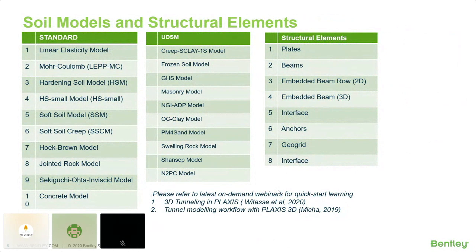Apart from soil, which is a continuum element, we also need structural elements. So we also have different types of structural elements, such as beam elements or plate elements. Plate elements will be very useful in modeling the shield of the TBM in the tunneling process, and other structural elements as well.